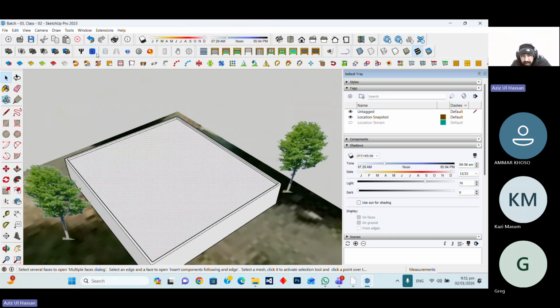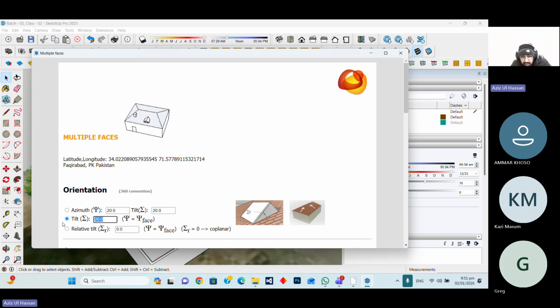Like we have made one layout where we give a 5-degree tilt angle, because in the shed we normally have to give less tilt angle, since they are heighted from the front elevations. And if we increase it, like give a 20-degree or 50-degree tilt angle, the back height will increase, and we have to increase the structure thickness and other things.